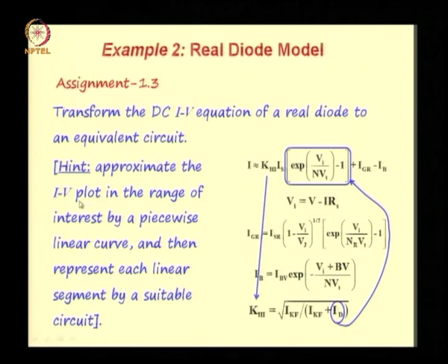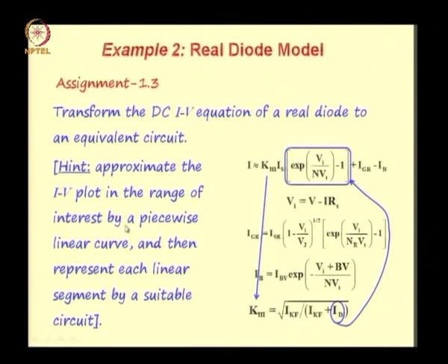So this is a hint: approximate the IV plot in the range of interest by a piecewise linear curve and then represent each linear segment by a suitable circuit.